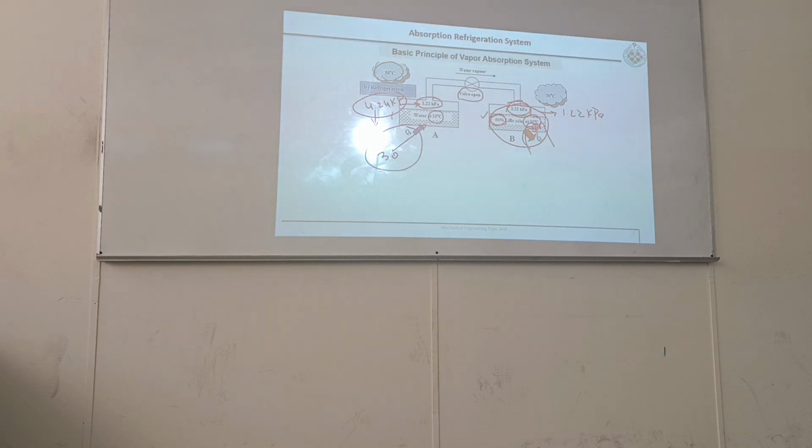Now, what will be happening in reality? After some time, this liquid water level will drop. At the same time, what is happening here? This 50% will not be 50%. It will rise. Rise means water level will rise. Lithium bromide concentration will drop, but water concentration will increase.